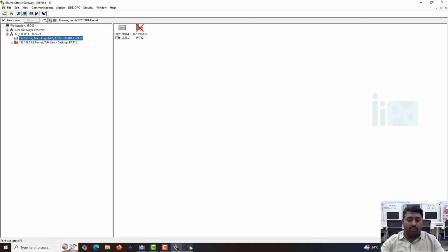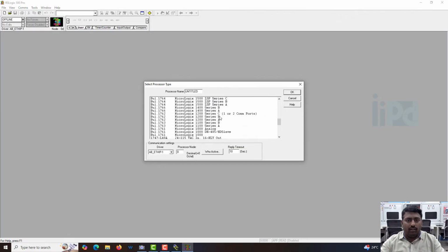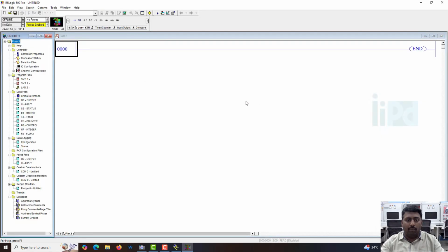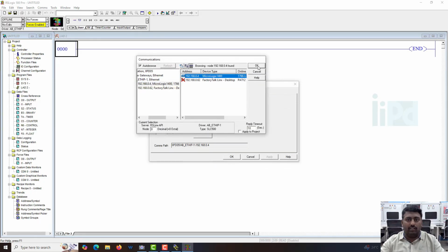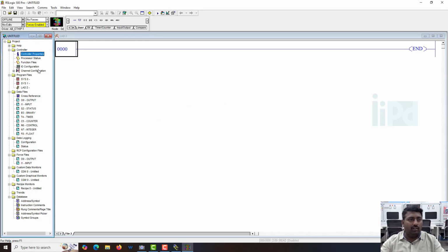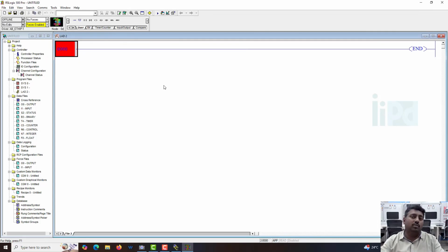Okay, so let's start. For that, let's open a new project. File, new. I'm having the 1400 series B. In the controller properties, let me set up which is the PLC, and apply. On the channel configuration, I will just set up the IP address since I'm using Ethernet to communicate. Apply. 192.168.4.x, subnet 255.255.255.0.